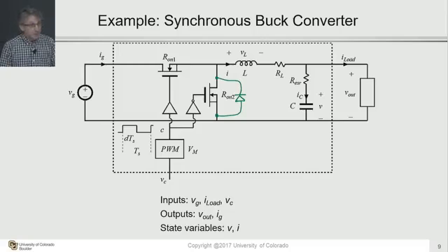Instead of a diode, we can employ an active switch, in particular a MOSFET, to have that switch conducting at a time when the diode would be conducting current. So when you turn off the main control FET, then normally the rectifying diode would be conducting automatically. You will have automatic commutation between the main control FET and the diode.